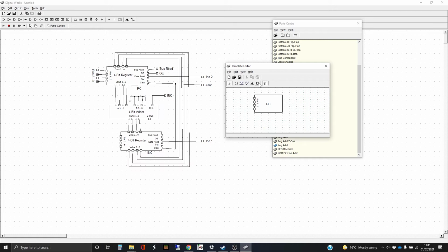No, what I'm going to do is put the phase controls, so the ink 1 and ink 2, at the bottom. And the reason for that is, if you remember the diagram that I've got of the architecture, I'm probably going to lay the CPU out very similar to that diagram. And so the ring counter, which is the thing that sends out these signals, is probably going to be underneath everything else. And so having them on the bottom where those lines can come in from below is entirely reasonable.